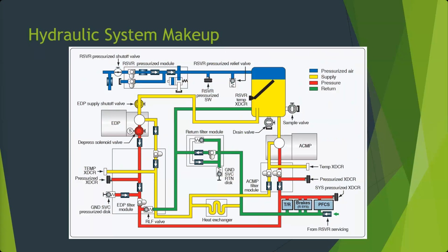If you also look downstream of the pumps in the manifold area, there's the relief valve here in the lower left. That sets, remember, your system pressure. So when the flow is minimal, the pumps can adjust their flow, variable flow, to do a low amount of flow but maintain that 3 or 4 or 5,000 psi, depending on the design characteristics of the aircraft. And that is set by this relief valve down here.